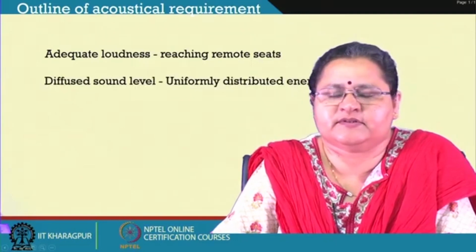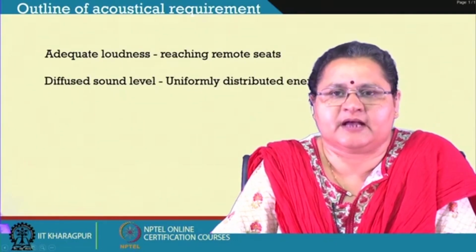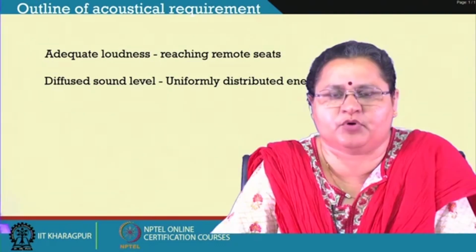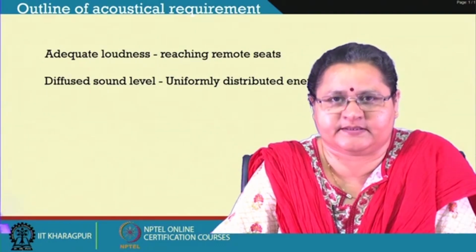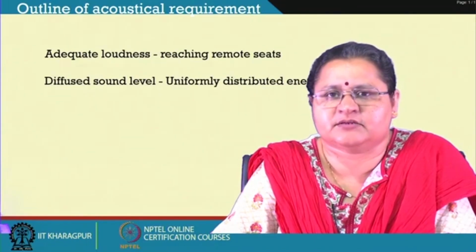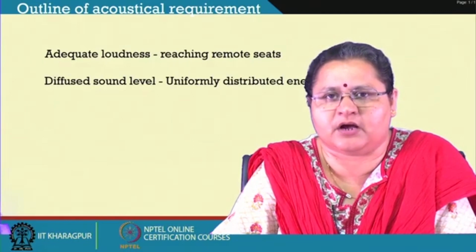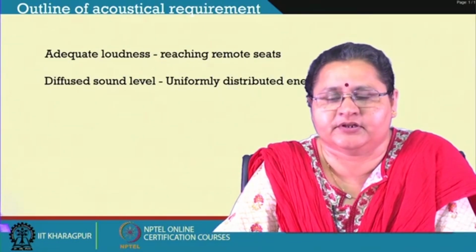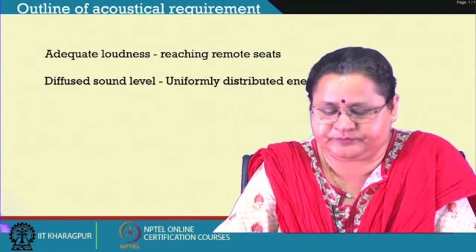We need diffused sound level, that means sound should not be specular, that is directly reflected sound should not reach individuals, so that it does not disturb them, nor create sound shadow zones or dead spots within the space. So, we have to be very careful, and it is best to target diffuse sound, which will give a uniformly distributed energy level within the entire space.